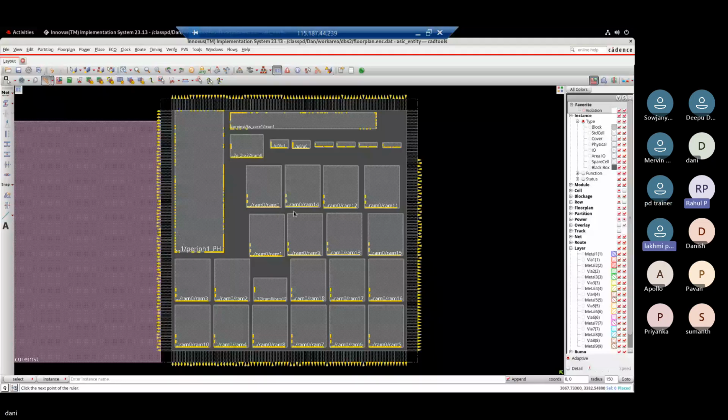What's the difference between placement blockages and routing blockages? Placement blockages means cells will not be placed. Routing blockages means you are blocking the metal layers from routing. Okay, so it is not allowing you to use those metal layers for routing. Yeah, those tracks of metal layers. So if M1 or M2, whatever metal layer, those tracks of that metal layer, we are not allowing to route. Maybe because of congestion, we are not allowing routing to happen with those nets.